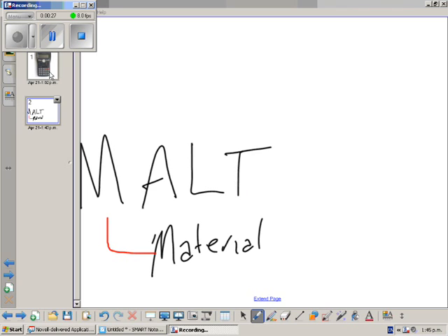Along the way, someone's got every material we use as a conductor, and they've got 1 cubic meter of it, and they've measured the resistance of it, and they've come up with a table. The values they got out of there, they called rho, and they gave it this Greek symbol, rho.